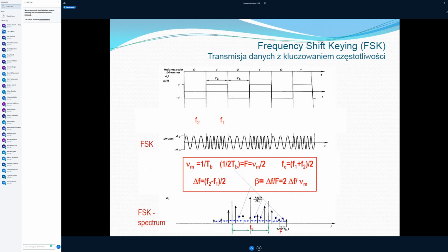But if we can imagine completely free data, completely random data, then our spectrum changing in each moment can be averaged, and then we say that we have the spectral density, and that's why we can draw the spectrum as an analog line, not discrete.